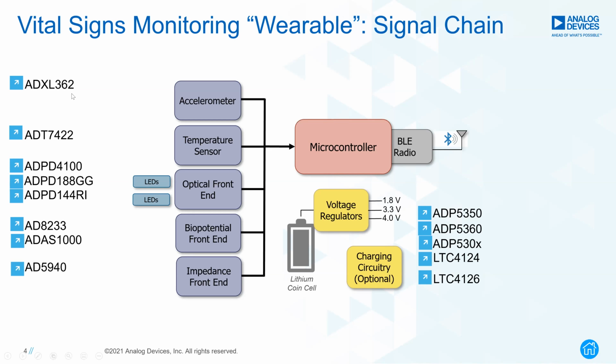This also has many specific features for wearables. For example, if you want to use this accelerometer as a wake-on switch, it has an option we call wake up mode, where you can use this device as a switch to power off all the circuitry when the device is not used or kept aside somewhere.